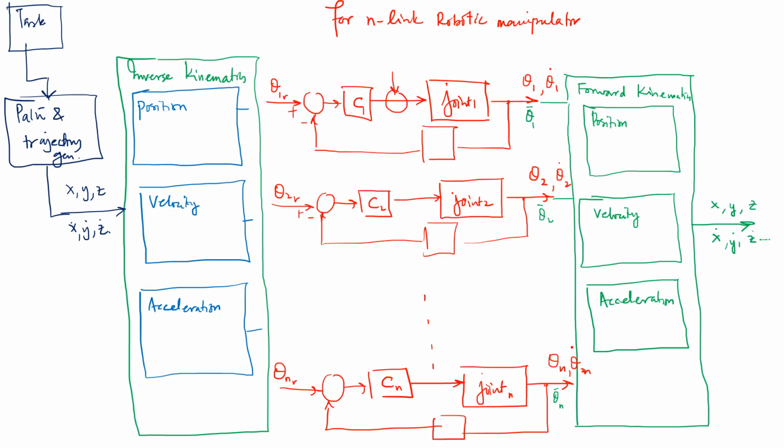And I should emphasize that the forward kinematics needs to be solved all the time, multiple times in a second. And similarly, inverse kinematics is simultaneously required to be solved again and again. So all the issues corresponding to singularities, existence of a solution, and uniqueness of a solution are going to become important in the inverse kinematics as well. But inverse kinematics itself is dependent on how the path planning and trajectory generation module has given this task in a structured form to this module. So you have to consider all these issues in conjunction with each other. These are not isolated issues. These are all related with each other, and that's why these need to be handled and resolved in this whole course.